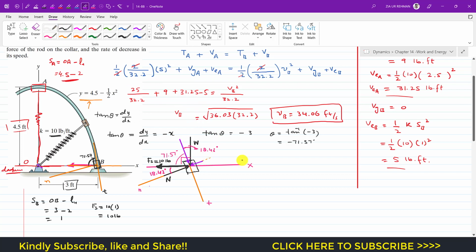So now if I apply the summation of forces along the normal axis, that will be equal to m a_n, and we know that a_n is v squared divided by the radius of curvature, and since the collar is at B, this will be v squared over the radius of curvature at B. So now we have to find the radius of curvature at B first before applying this equation. As we know from previous chapters, the radius of curvature is equal to 1 plus (dy/dx) squared, to the power 3/2, divided by the absolute value of d²y/dx².